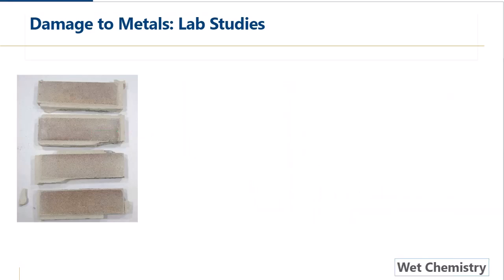But we also wanted to look at a different area of the mortar and understand about how much degradation it might be from the hydrochloric acid, and whether there's still chloride in there that could lead to additional corrosion of the aluminum. So in this case, we took a sample of the mortar, we ground it up, and then we did what's called a water extraction. So we mixed it up with water, stirred it up good, and then let stuff dissolve in the water, and then filtered out, so separated the liquid from the solid.